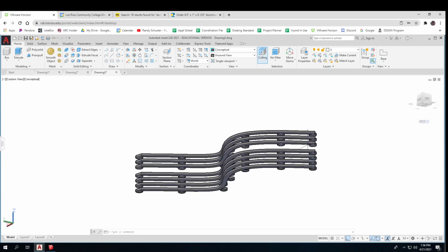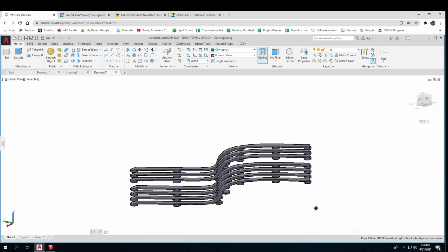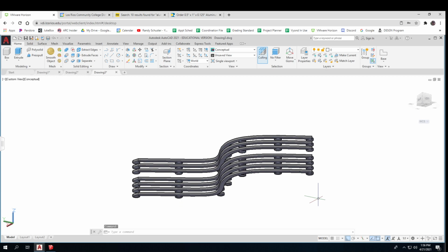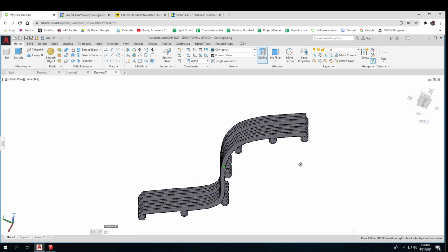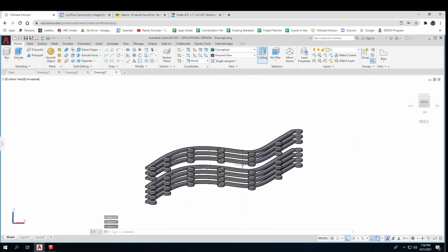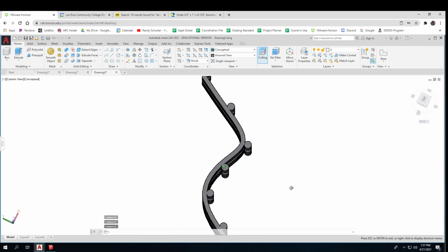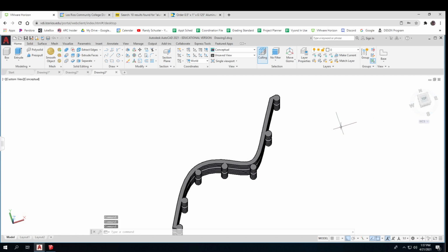So this ability to make slices and then just put some spacers in between and put a rod in is a very effective way to make complex shapes from flat, plasma cut, or laser cut. So that's kind of a neat idea that you can play with too. All right. So there we go. There's a few different ideas for you and a couple of demonstrations.